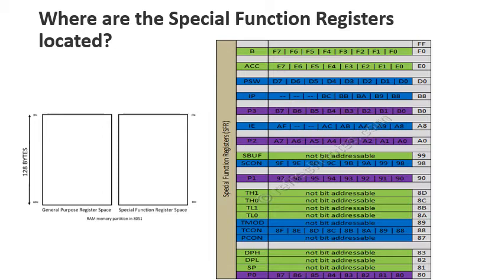But storing normal program data in this RAM space is not possible. Therefore, the 8051 microcontroller has an effective general purpose RAM space of 128 bytes, that is from 00H to 7FH. Looking at this picture, you might be wondering, can one place data in the empty space? Well, it is not possible to write data in the SFR space even if some places are empty, as they are kept free by the manufacturer to add functionalities to newer versions of the same microcontrollers.